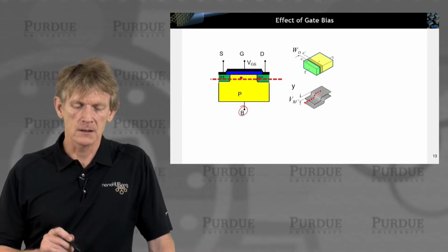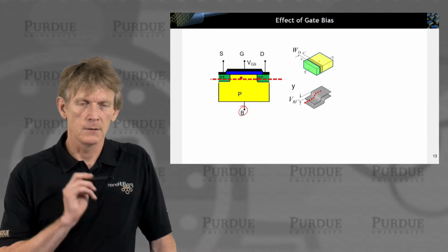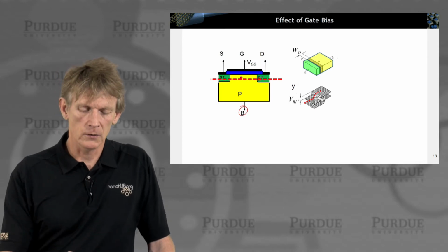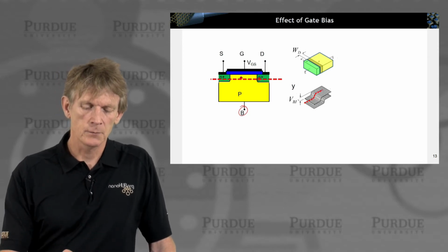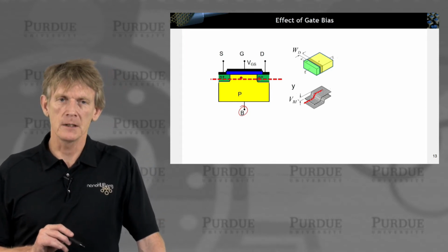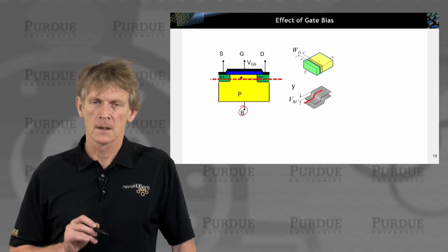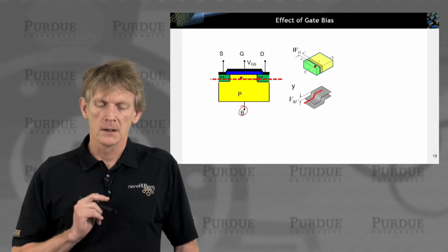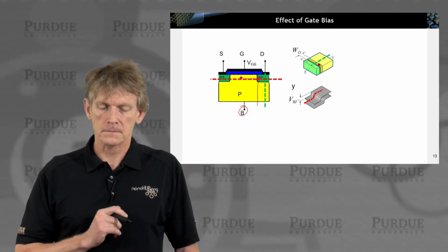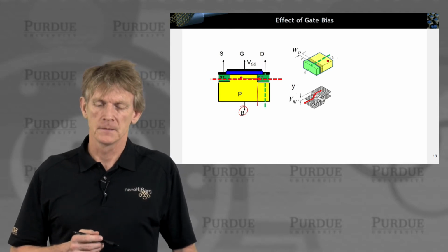Well, in that direction, it goes from heavy doping N to p doping, and this is just like a p-n junction where we're looking at an electron experiencing a built-in potential from an NP junction, if we're just looking on this segment here, okay? All right. Now, if you're looking for an electron marching in this direction, it also sees an N plus P junction.